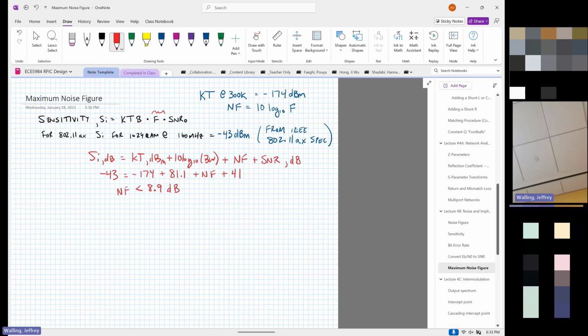So the other major thing that we care about in a radio system is noise and linearity. Anybody can receive a signal if they have a perfectly linear channel with no noise in it. I can give that to most undergrads, and they can probably figure out some way to collect the signal and receive it. Where RFIC designers make their money is by being able to design systems that can receive signals in the face of strong nonlinearities with lots of noise.